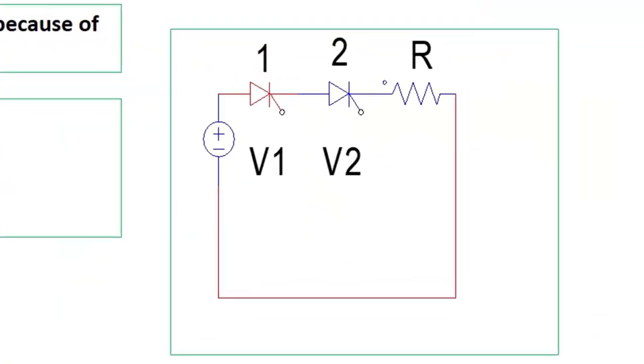Voltage shared by the two SCRs may not be equal because of the inherent variations in their characteristics. The reason behind it is that at any instant of time, the number of carriers across the individual thyristors, though they have the same rating, same part number, same specifications, are not equal.